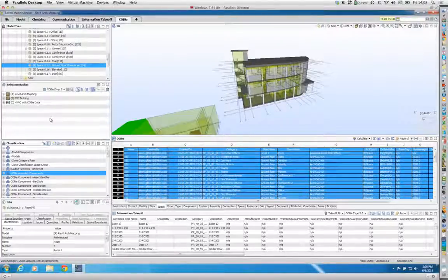So it's a good example in the fact that IFC doesn't have as far-reaching functionality at the moment, and sometimes you have to use the categories in the IFC file to put some different items onto it. So, for instance, there's no drainage elements. In an example I've done in previous times, where you've got a drainage component like a rodding point or a rodding access point, inspection chamber, those inspection chambers may end up on something like pipe fittings, and you might not want to display all of the pipe fittings.